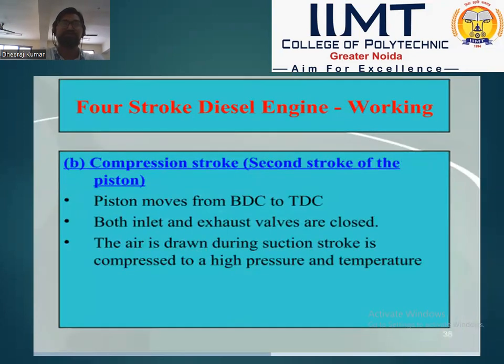The second stroke in a diesel engine is the compression stroke. The piston is at its lowermost position and moves from BDC to TDC. Both the inlet and exhaust valves are closed. The air drawn in during the suction stroke is compressed to a high pressure and temperature.